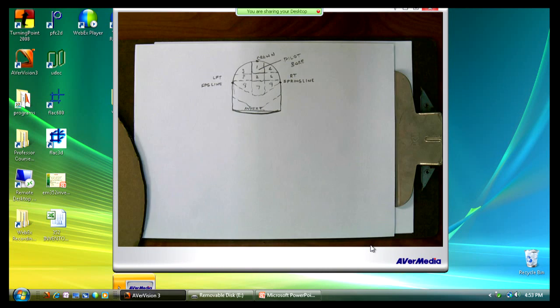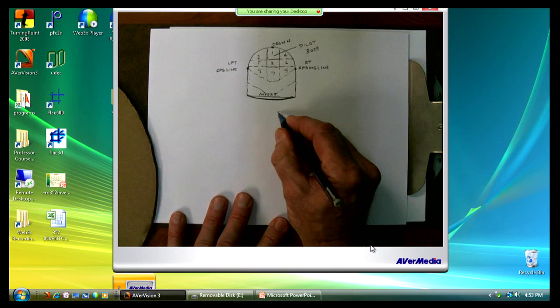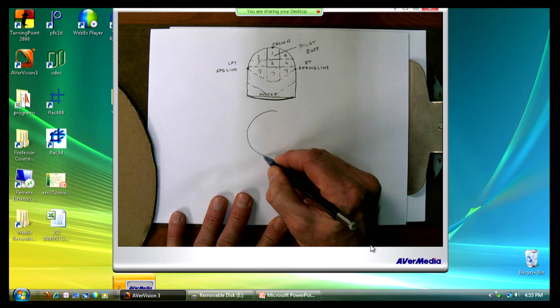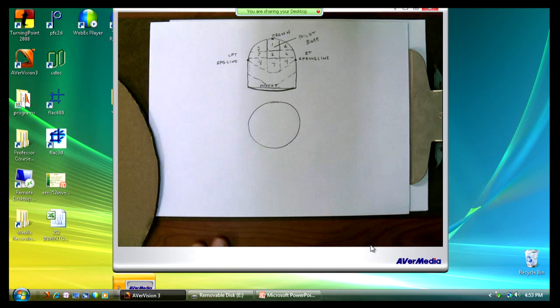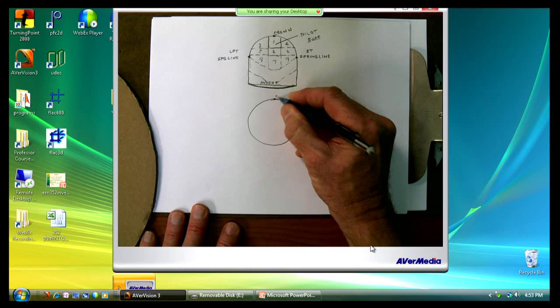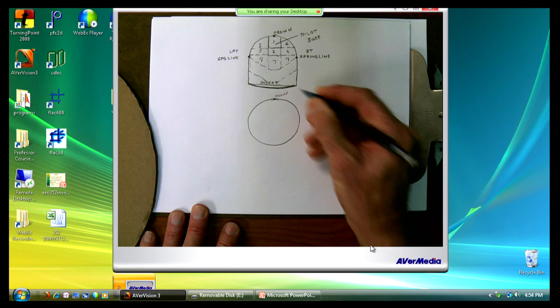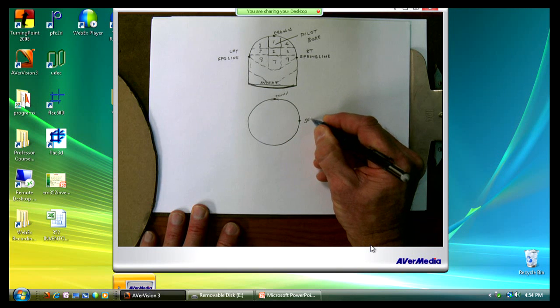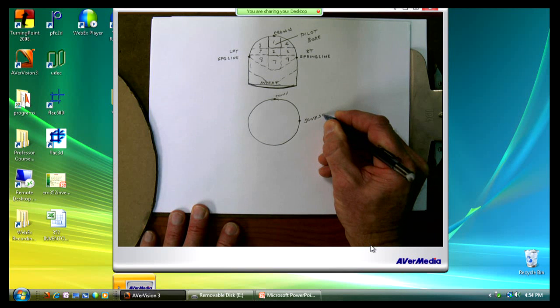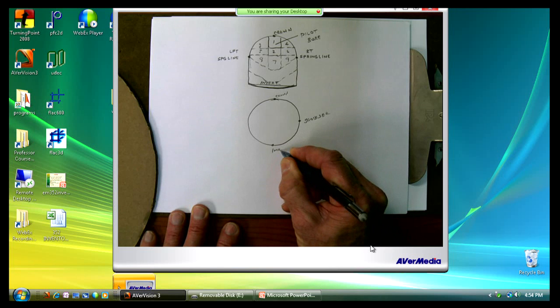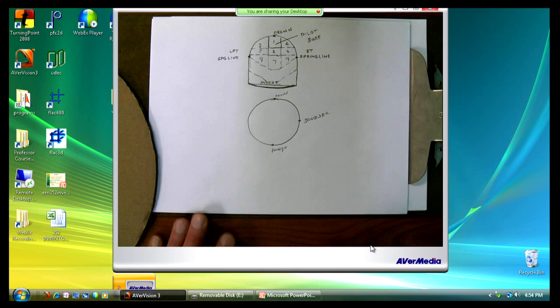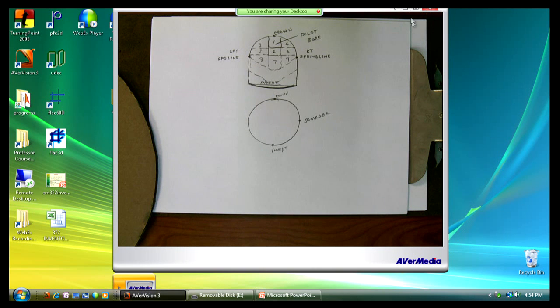So today with tunnel boring machines, which are the norm, we're doing it full face, all at the same time, typically circular. We'd still call this the crown, and we call this the shoulder in that case. And we call this the invert still. So the invert's the bottom. And then you have stationing along the way that you might see on here.